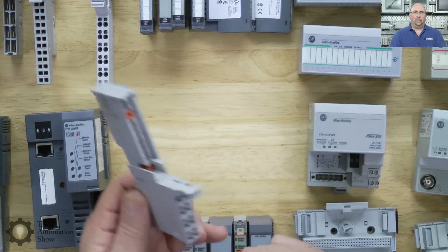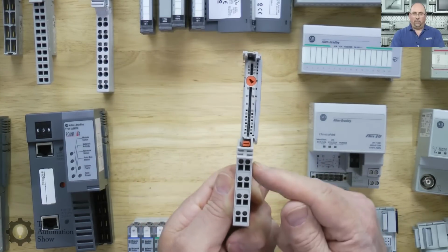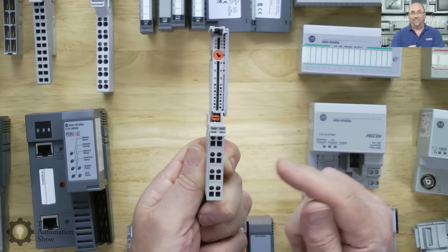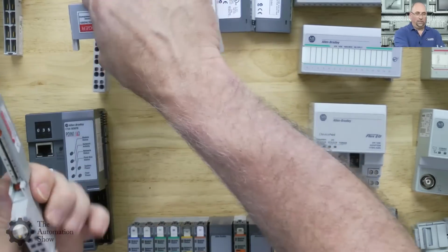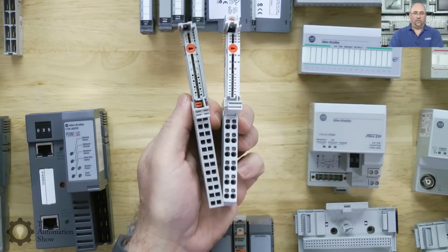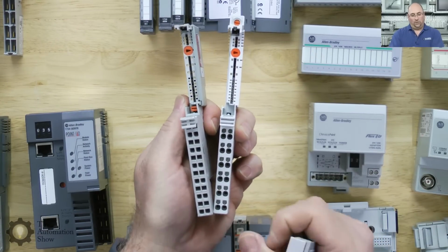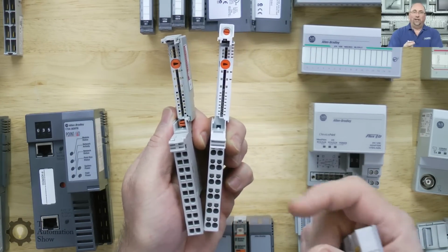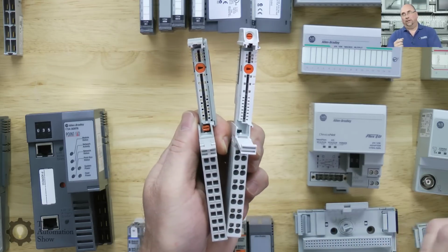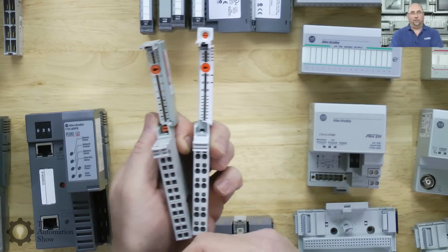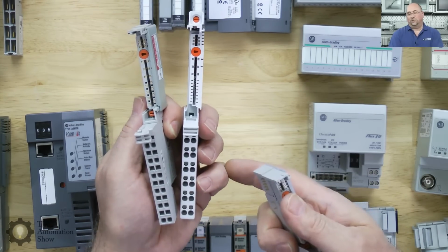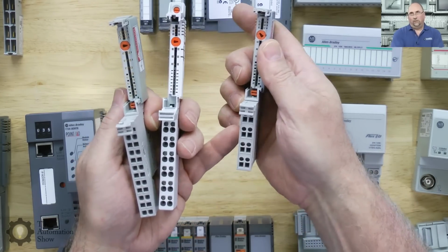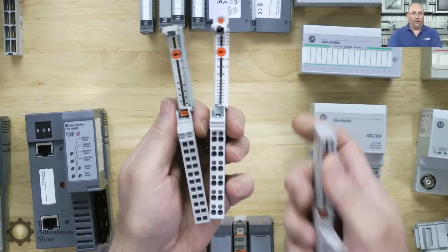The other thing is that with Point-IO, the maximum number of unique terminals you can have is 8. The most dense module you're going to have is 8. Now, if you look at some of these other terminal blocks, here, let me get them up here. You'll see that they actually have 12 terminals, but there are only 8 unique ones there. 7 is tied to, I think, 11, and 8 is tied to 12, and so on. So the last 4 are just internally tied to 5, 6, 7, 8. So you're not getting extra terminals there.